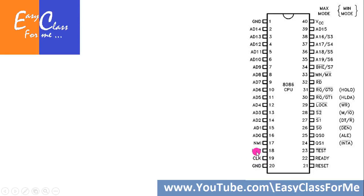Now here we can see we have INTR and NMI. INTR stands for interrupt and NMI stands for non-maskable interrupt. These are essentially the same kind of thing. INTR means whenever the processor is performing some task and you give it a new task to perform, the processor will see if it is busy; if so, it will say, I will not perform your task because I am busy, and if it is not busy, it will accept your interrupt request. Interrupt literally means that you are interrupting something or somebody to give them your task. That is why this interrupt pin is used. And this NMI is also an interrupt, a non-maskable interrupt. Masking means you are suppressing somebody.